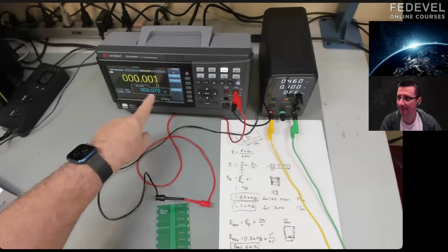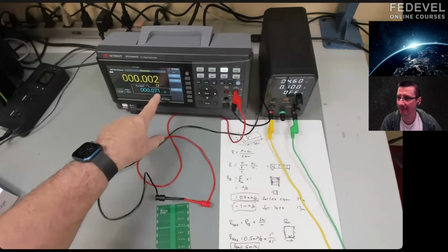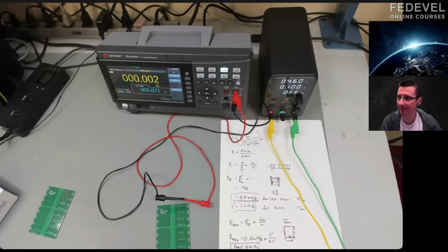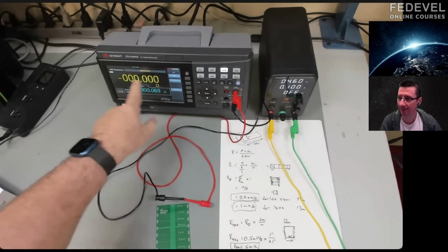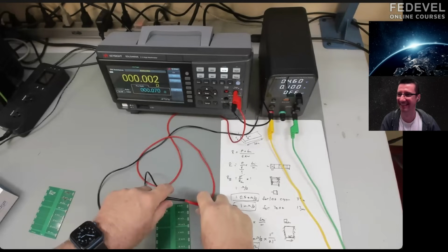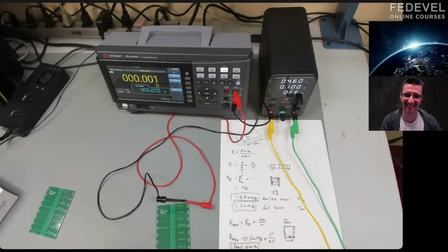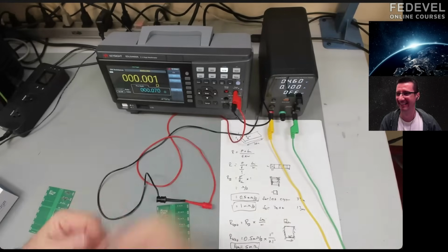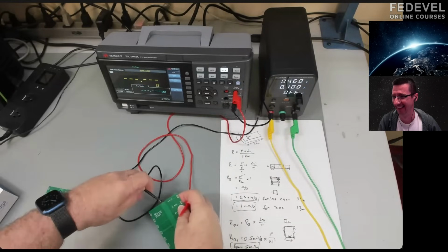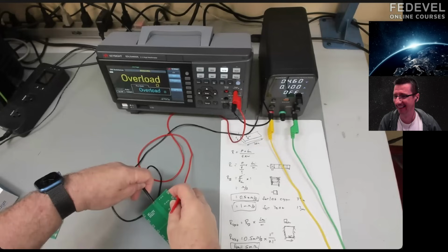And this is the value that it measures directly. It subtracts off that 69 milliohms. Here's the residual measurement. So it's showing us the raw measurement and after it did the zero subtraction. I'm not sure I would say calibrated, but it's subtracting off the offset. So now let's remeasure our trace.